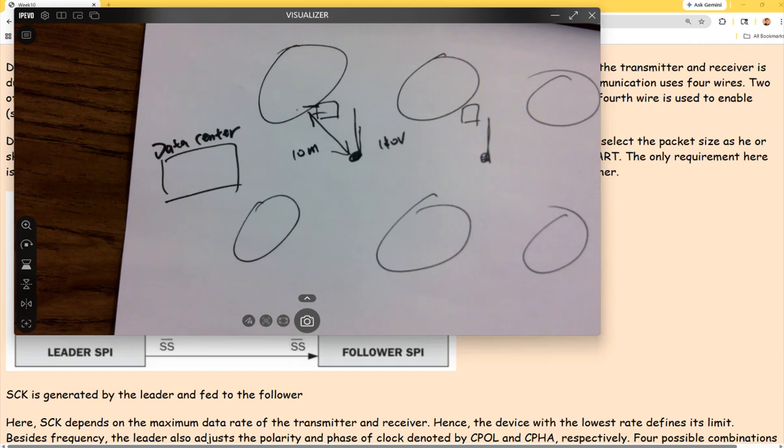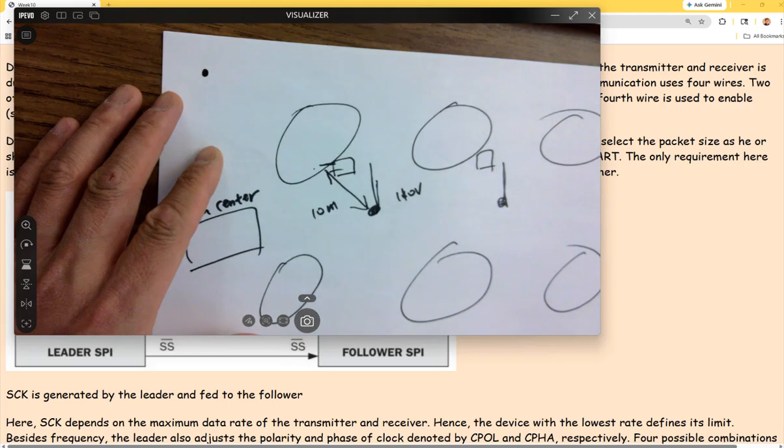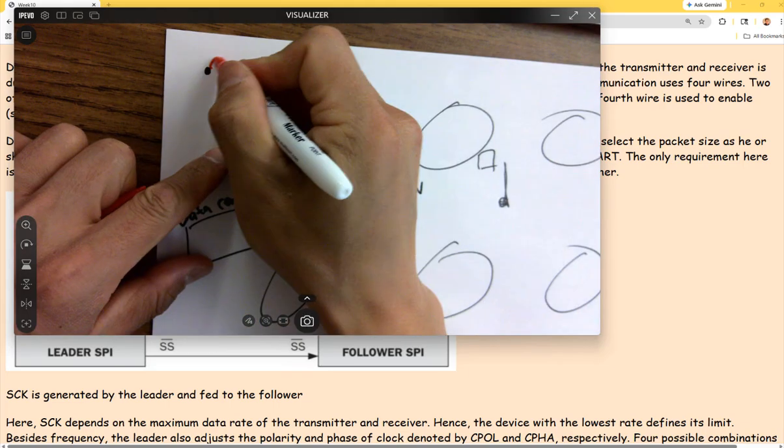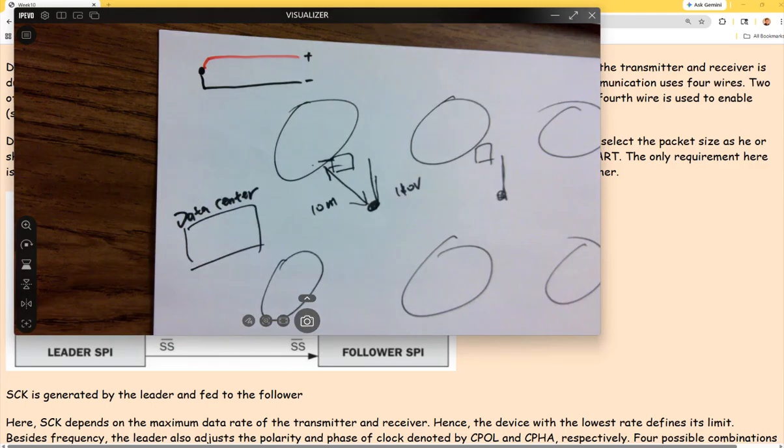Would you guys propose some solutions to it? So first, what type of temperature sensor should we use? So there are multiple options. Thermocouples. Have you used thermocouples in M&I? Thermocouples is what? It's just like two metal pieces attached to each other, and whenever there's a temperature difference, it's going to reflect the temperature difference to the two terminals of the metal wires, and there will be a very small voltage change, right? A thermocouple is like a little metal junction here, and you have two wires. And you are seeing an analog voltage change according to temperature changes.